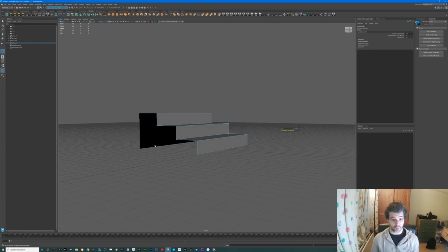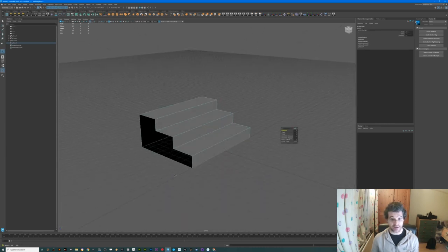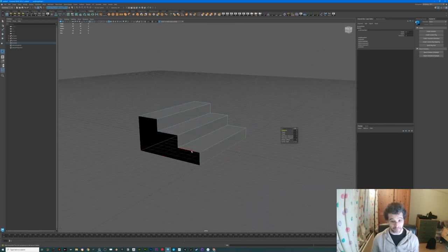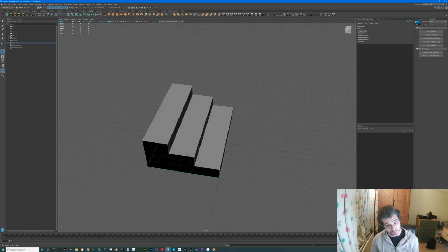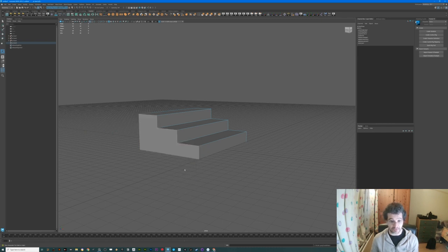So now I'm going to come here and right mouse click, select edge mode, so shift select these two edges. Now shift right mouse click and select bridge, and now I have a bridge. I've effectively closed down this area. I'm going to double click on this edge, selecting this loop, and now I'm going to shift right mouse click again and select fill hole.